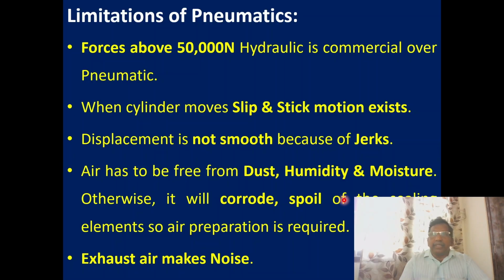When the cylinder moves, there is stick-slip motion. So we can see that when you want to start after rest, stick-slip motion will be there. Displacement is not smooth, so jerky motion and noise also will be there.